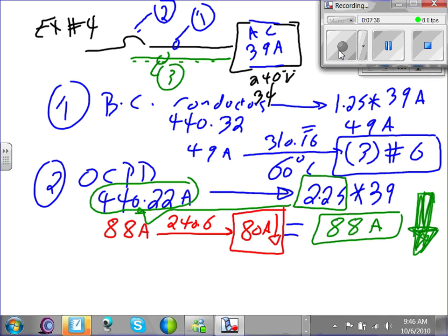It's not to exceed. For the motor, Spencer, it says the same thing, except there's an exception. One of the exceptions underneath the table of the motors says if you did not hit the standard, no problem, go up. That's why we go up in the motors. That's the code, guys. Sometimes they put an exception there. For this, just remember, for the HVAC equipment, no exceptions. You just go down. And that's 440.22, the overcurrent protection computation by 440.22(A).